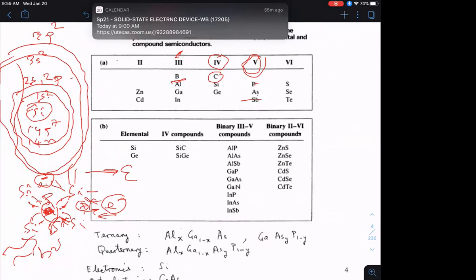All right. So I've kind of given an idea of how we can change the electronic properties in a very carefully controlled fashion and make a semiconductor more and more negatively doped. That's why it's called an n-type semiconductor, or p-type doped, or positively doped by putting in column 3 impurities. Okay. Now, from this part of the periodic table, you can also see how you can make other types of more complicated semiconductors. So if I'm just in column 4, based on elements, those are called the elemental semiconductors, but